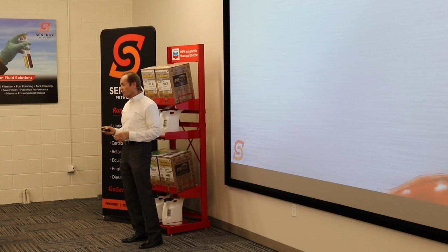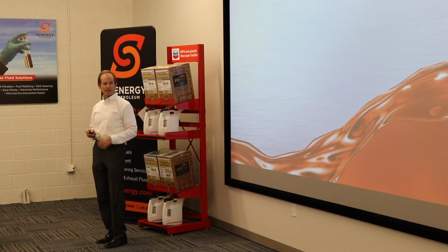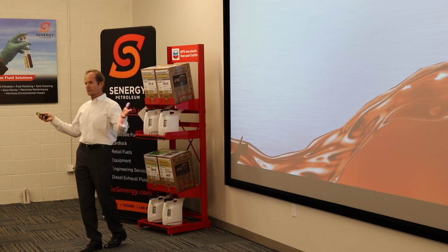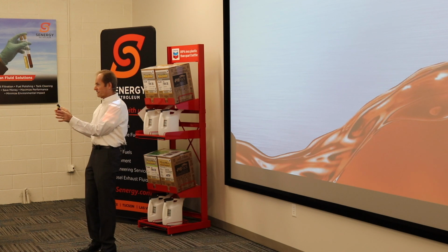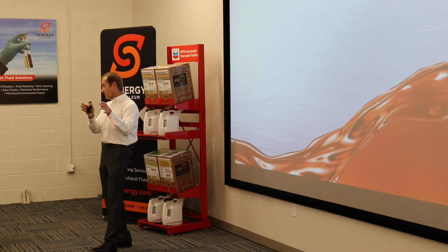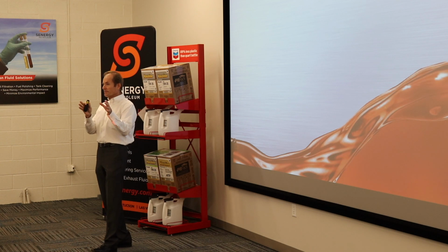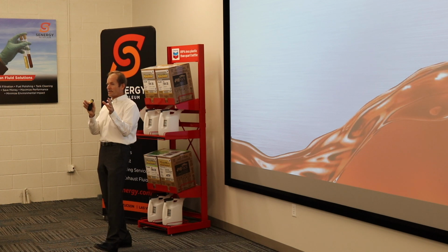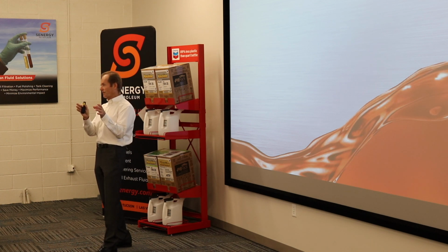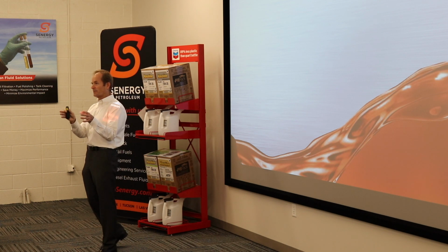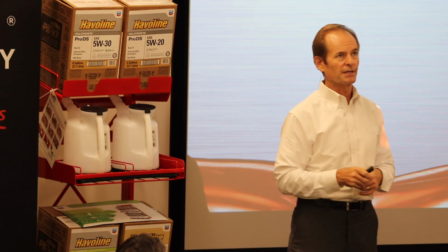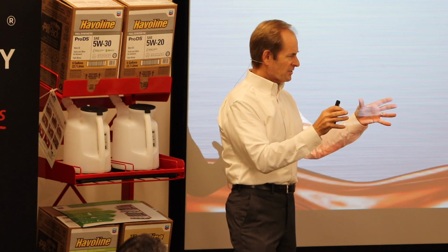In terms of what we ask an automatic transmission fluid to do, I'm going to go over that a little. And you remember that transmission fluids are the same basic formula we had for engine oils. We've got a base stock, we've got additives. Our base stock in transmission fluids is more likely to be synthetic, or at least a synthetic blend. What we ask it to do, the kind of conditions we ask it to meet, and the very fact that people don't change their transmission fluid, really call for it to be a synthetic. It's a really good fit for what a synthetic has to offer, and that is relatively long life, right? So that's your base stock story.